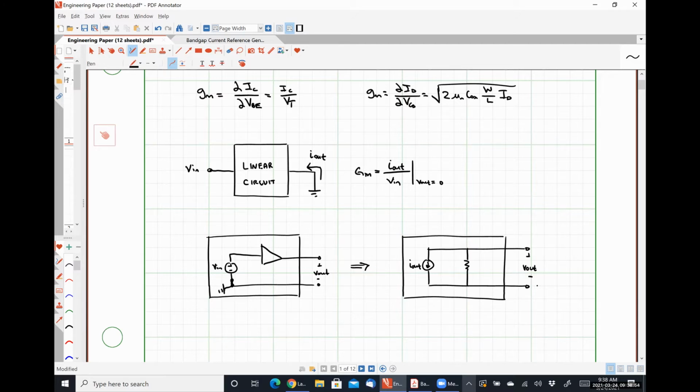So the resistance that we are looking for is actually the exact same thing as the output resistance of all of the amplifier circuits that we've been looking at. We short out our input voltages, we turn off all of our DC sources and all that kind of stuff, and we're looking in through the output terminals. So this resistance right here is nothing more than the R out that we have, hopefully at this point, effectively beaten to death on how to figure out, okay?